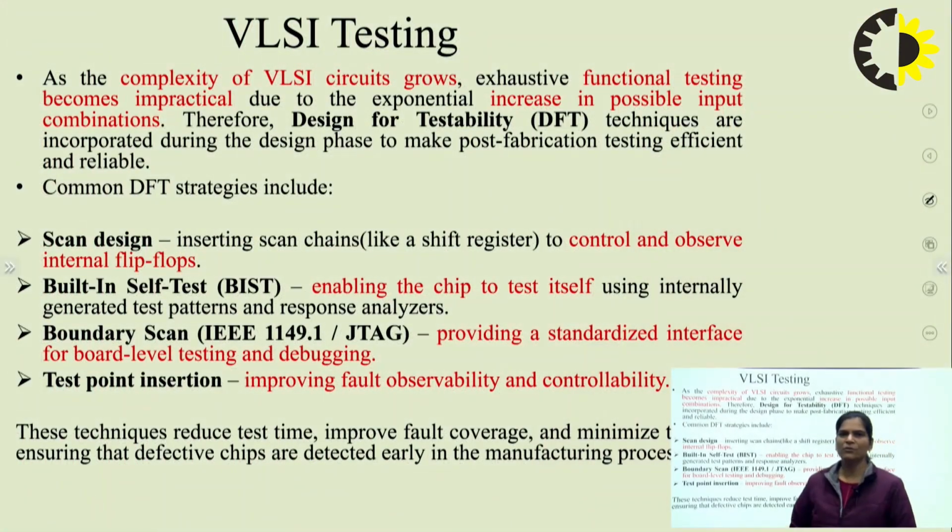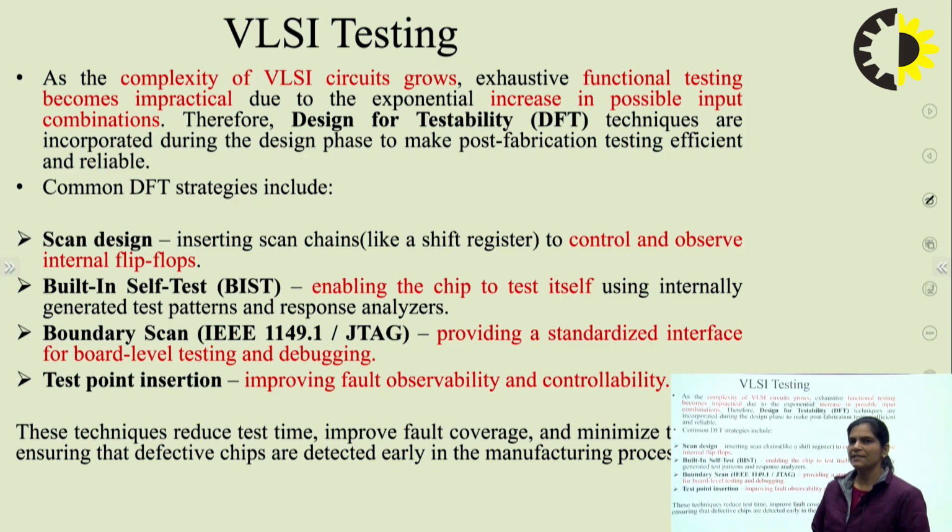Now, as you all know, in the VLSI flow, the complexity is increasing. So that's why, exhaustive functional testing becomes impractical due to this exponential increase in possible input combinations. Therefore, design for testability techniques are incorporated in the design phase to make post fabrication testing efficient and reliable.